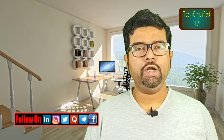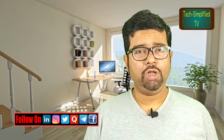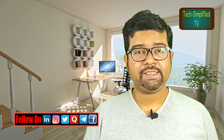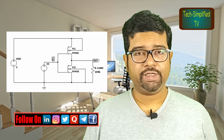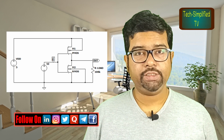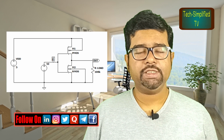Hi folks, you are already familiar with the LTSpice UI and toolbox. In the last couple of episodes, you have become familiar with the basic active and passive elements. In this episode, we'll construct a CMOS inverter using two monolithic P and N MOSFETs, where the P MOSFET has double the area of the N MOSFET for mobility balancing for majority and minority carriers of the respective MOSFETs.